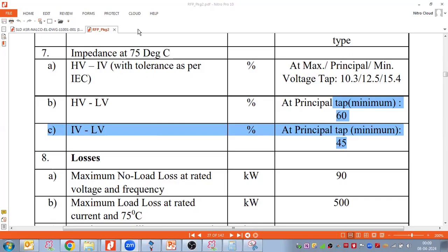What is the voltage system for your transformer? And we do have SVC, SVG. Nadim, your query is not clear to me. Oh yes, sorry, I was sending the message for another participant who was asking about reactive power. We have a static VAR generator, a kind of reactive power generator to compensate reactive power and harmonics. The same we can take from the transformer.